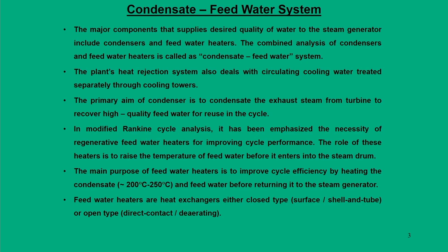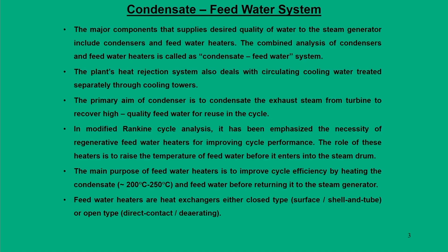So, that is the reason, and in fact, whether you look at the condenser or the feed water systems, water is directly supplied from the atmospheric reservoirs. So, all these things come under a single entity, and we call this a feed water system. Moreover, the feed water is normally supplied at an elevated temperature to reduce the boiler load. That is another kind of requirement that we need for this power plant system. All these needs have to be addressed by the thermodynamic concepts which we discussed earlier, that is, through regenerative cycles.